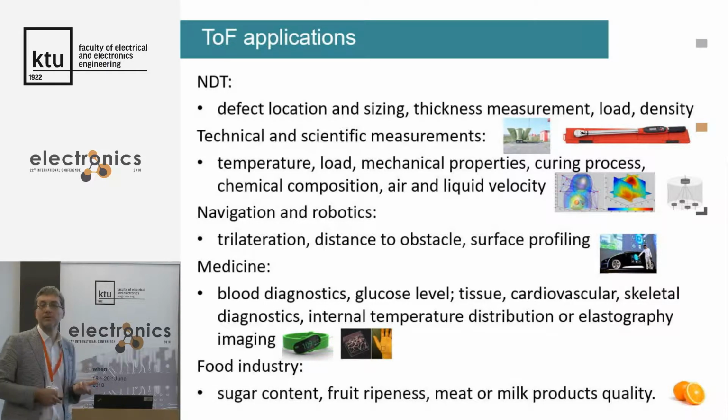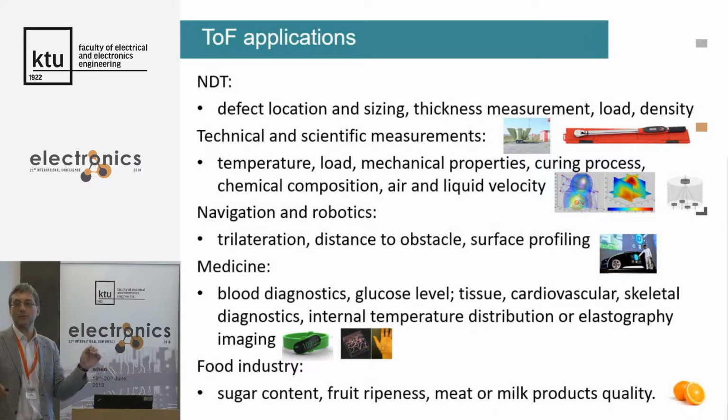For instance, you can measure the load. For instance, there was a project with Bosch. When they assembled the car, they wanted to use a lot of bolts, but every bolt has to be as small as possible because the total weight of the car is finally huge. What is usually done is that there is a wrench which has a limitation in the torque, and once the torque is limited, you are no longer tightening the bolt.